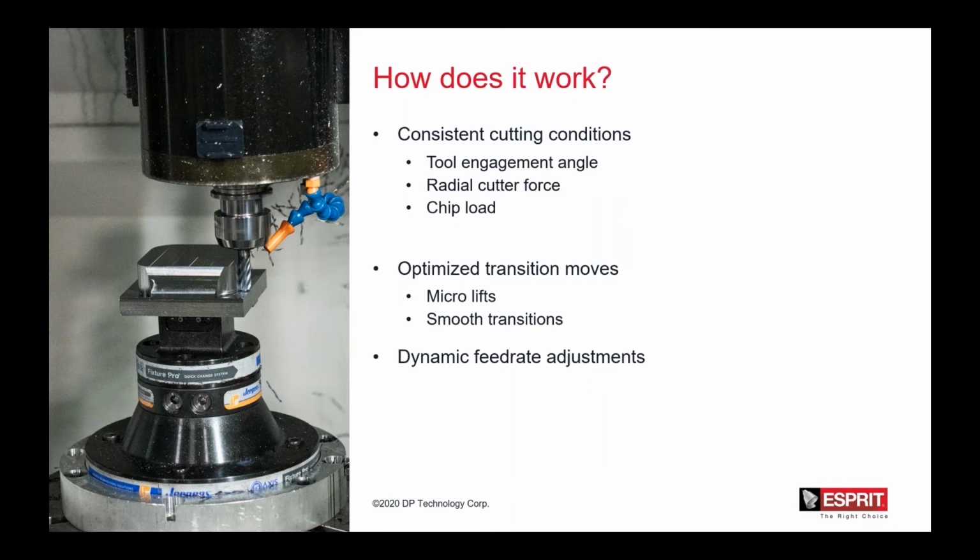And like I was talking about before, we have dynamic feed rate adjustments where it's constantly adjusting that feed rate during the cycle based on that engagement in material. So you're never really getting too heavily engaged in material. It's just a constant chip load that you're achieving there.